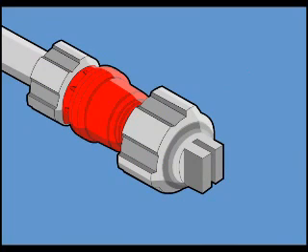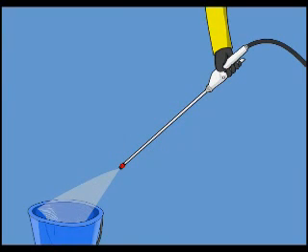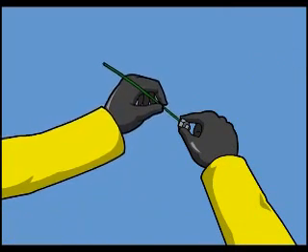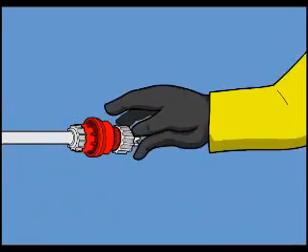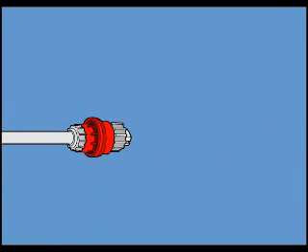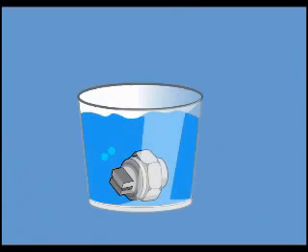It is not always practical to have spare nozzles in the field, and blockages in nozzles are a regular occurrence. Ways to clean a blockage from a nozzle in the field are to place it on the pressure release valve on the pump and let the pressure blow the nozzle clean, or use a soft piece of grass. The correct recommendation is to replace the nozzle and soak the clogged nozzle in water in a clean pan.